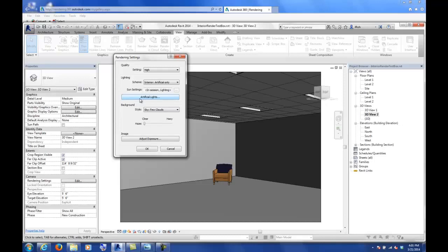One thing to keep in mind, and you probably know this from other rendering experience, is that when you render this camera view, even though I'm in this room, it's still rendering all the other spots of your model somewhere off into space, even though you don't see that. So what that's going to do is add more and more time to your rendering. Therefore, what you want to do is probably turn off all the lights that don't pertain to this room.